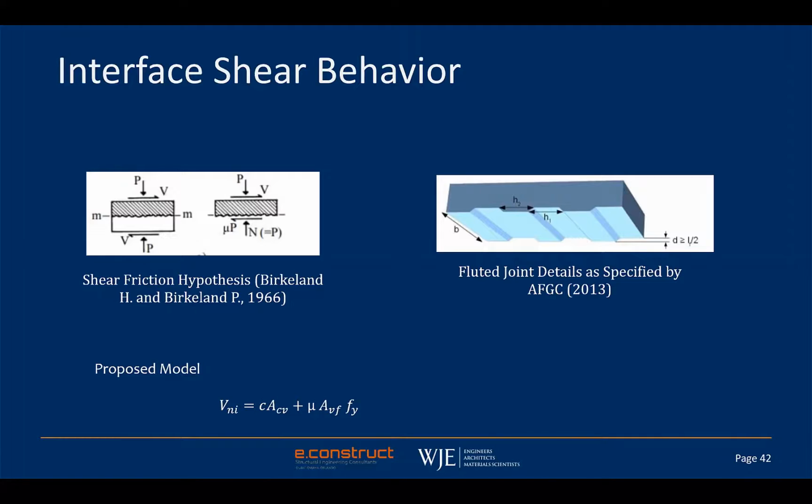The equation that we are proposing to use is the same standard form that we have been using for years for AASHTO: a cohesion factor times A plus a friction factor times area of steel times Fy. Except in this case, really, there's no cohesion. That concrete is impervious. There's no paste that can penetrate through and create that cohesion. It's like glass.